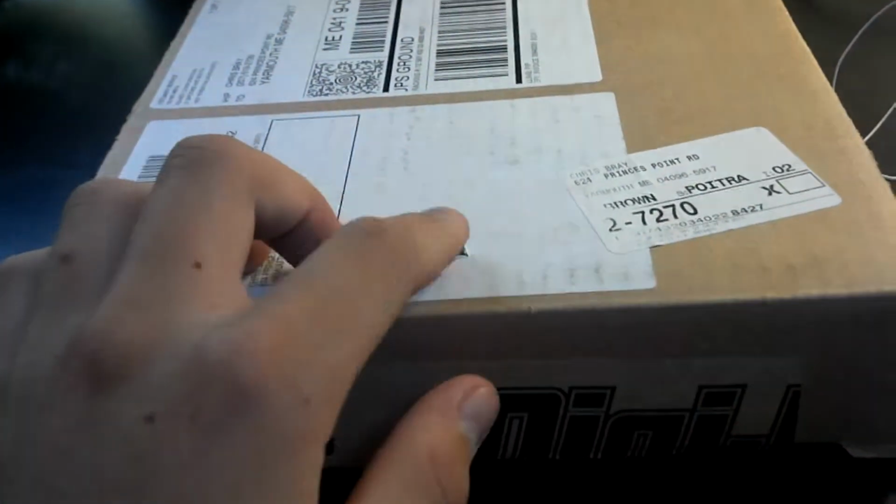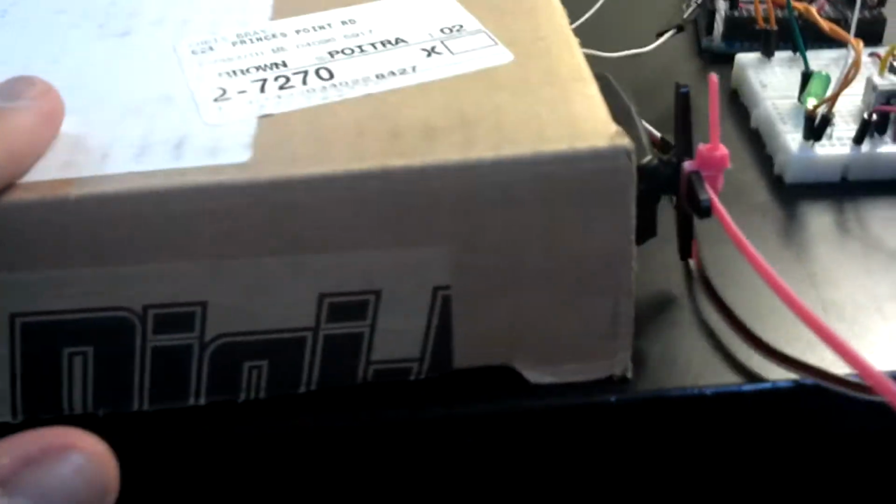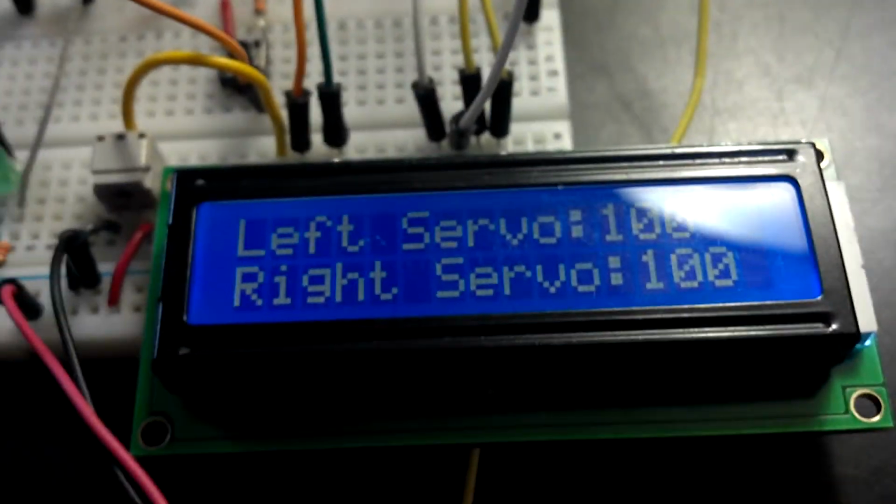There's an LED up here, there's a servo with zip ties on them to show essentially what angle they're pointing, and this can simulate, like the LED would simulate the PWM value that would control the ESC, and the servos would simulate steering servos. So there's an LCD right here that I've been using for debugging. This is a clone Arduino Mega, but I'm not using any of the Mega features. I just needed it because I've got my other Arduino over there. I don't know if you can see it. The other Arduinos I'm using as a programmer for tiny AVR stuff.